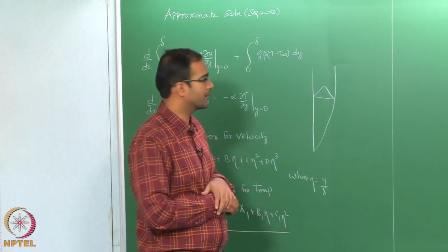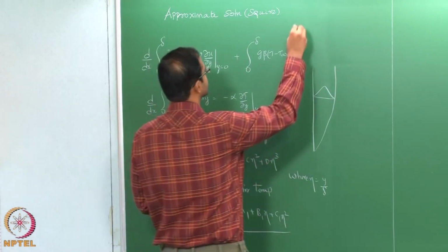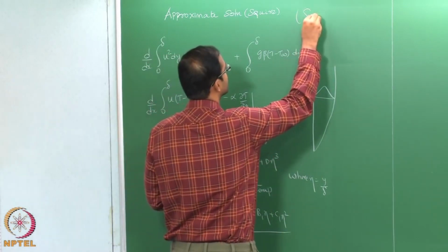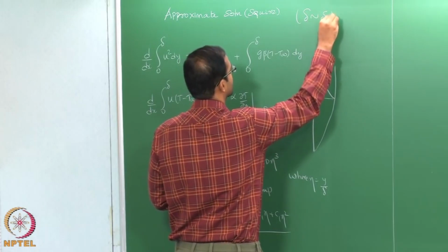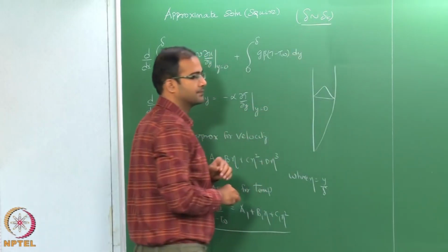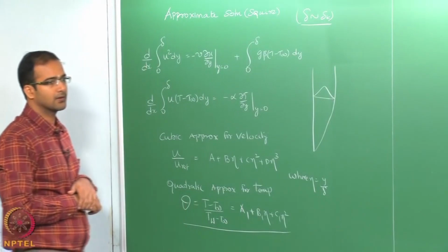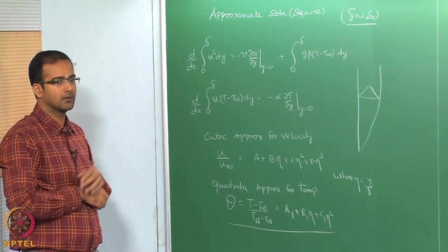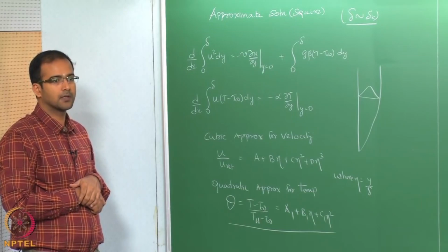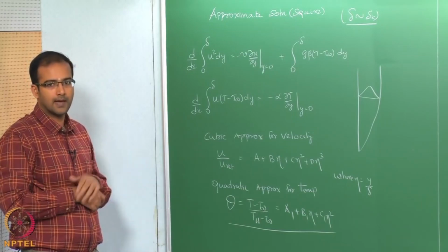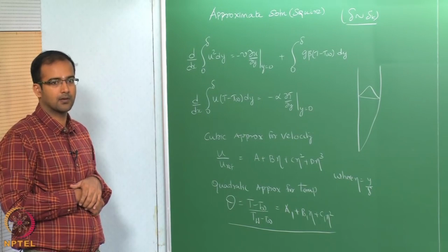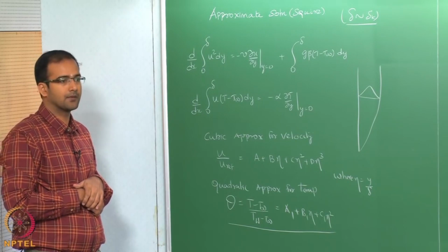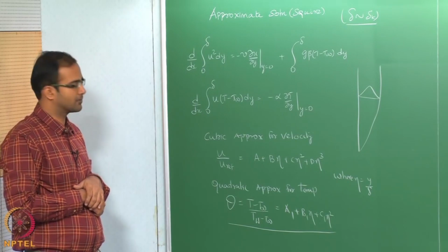However, we have only two equations. Therefore, he made the assumption that the two boundary layer thicknesses are approximately the same. This is valid if your Prandtl number is close to 1, between 0.7 and something like 1.2, 1.3, which most of the gases are within, and therefore this is not a bad approximation to make.